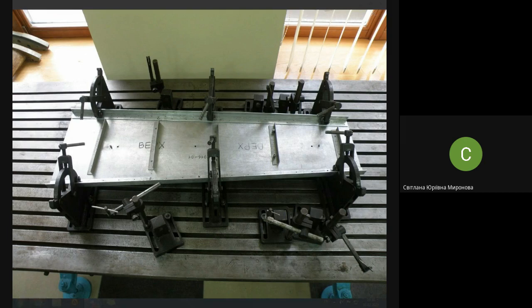And you see that in order to save money, and because the demands on the accuracy of these stiffeners are not high, stiffeners are also located by assembly holes. The question is, why do we say that we locate in a jig, or we assemble by jig, if we use at least 2 different methods of locating in a jig?